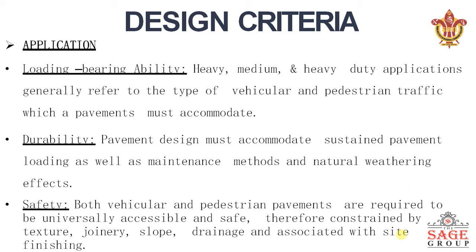Depending upon the load, light, medium, and heavy-duty applications generally refer to the type of vehicular and pedestrian traffic which a pavement must accommodate. Durability: pavement design must accommodate sustained use as well as maintenance methods and natural weathering effects. Safety: both vehicular and pedestrian pavements are required to be universally accessible and safe, therefore constrained by texture, joinery, slope, drainage, and associated site finishing.